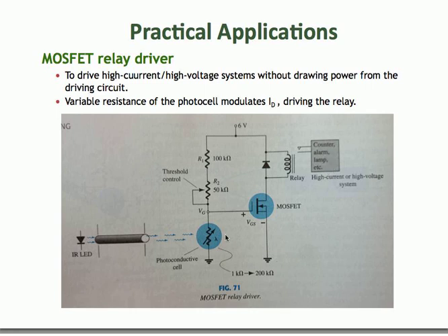But when the light sensor is exposed to very little light, the resistance of the photoconductive cell goes up. If you use KVL, the voltage division rule, when the resistance of this part goes up, VG will similarly go up, and the increase in VG will draw more current from the voltage source.